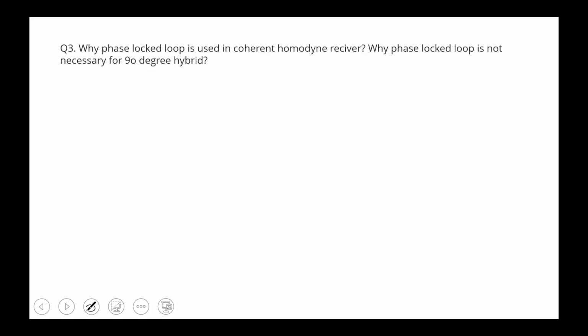We put one phase lock loop on the output side. We compare the input signal with the output signal, and then we suppress that noise. So it is not backscattering, not the I2 component or I1 component outside of our balanced detector. We just compare the signal with the local oscillator signal, and we compare the phase, amplitude, and frequency of the local oscillator through the phase lock loop only.